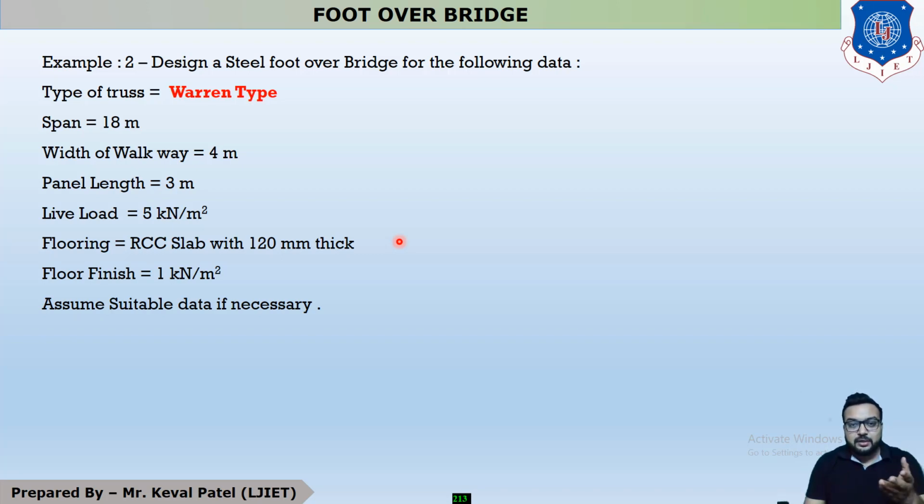You all know that for 20 mm diameter and 4.6 grade of bolt, the bolt is in double shear, because we have to use double angle. The value of double shear for 20 mm diameter is 90.52 kilonewton. It means if we fix one bolt, it takes 90.52 kilonewton load.